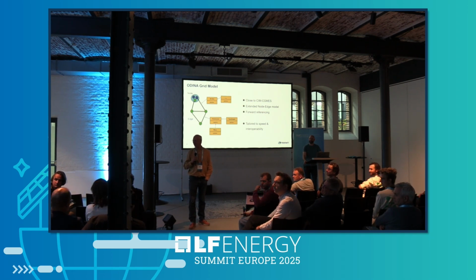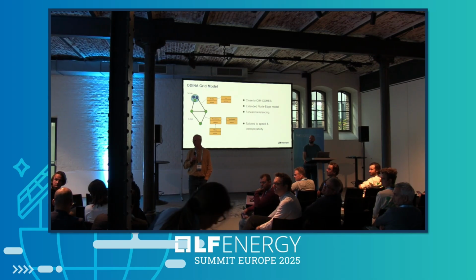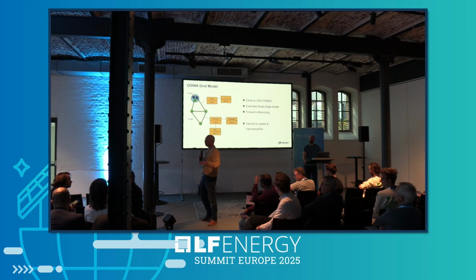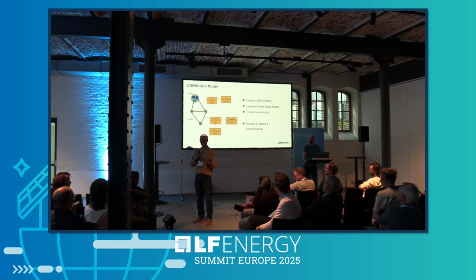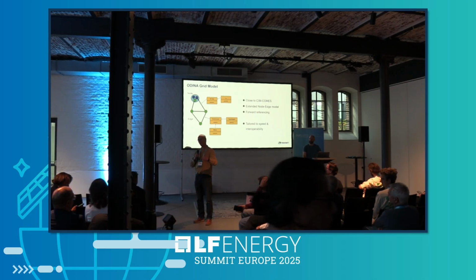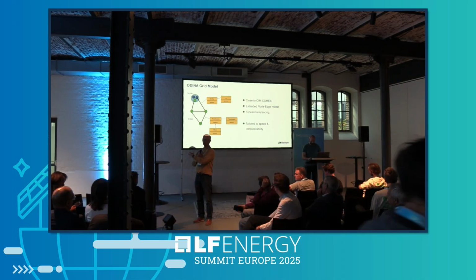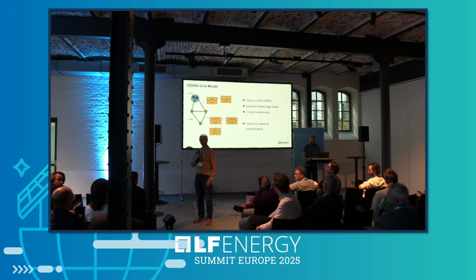I saw that there is the linear power flow. How is it connected to PowerFactory? We only use the network model. So PowerFactory for us is nothing more than a network model editor. There's a network model there. We open the API, take all the objects, parse them to our model, do all the calculations in ODINA, and only the results are then exported back to PowerFactory.